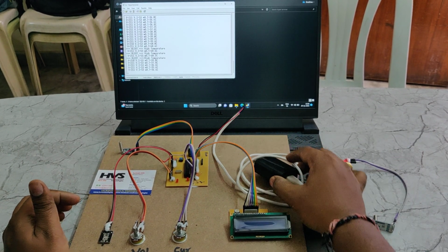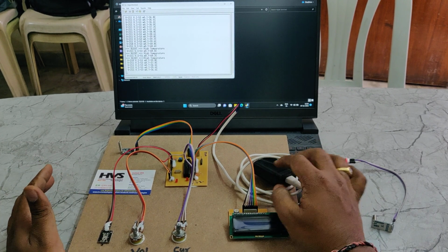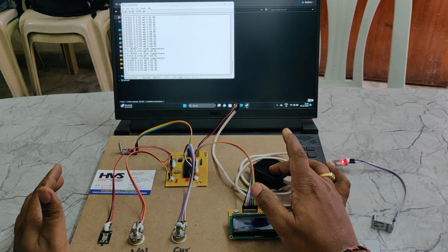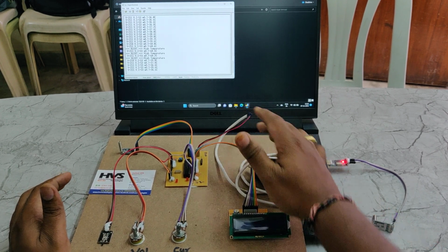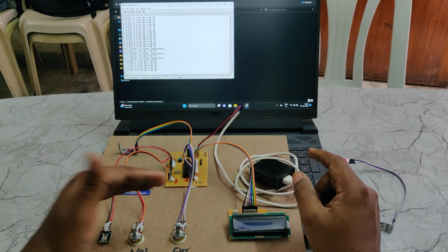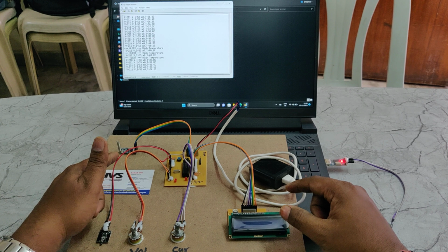microcontroller. The whole system gets its power supply from this adapter at the transmitter unit, and this adapter takes 230 volts AC input and provides 5 volts DC output. Once we provide that 5 volts DC, it starts reading input from the input sensing modules and controlling the output modules along with data transmission.